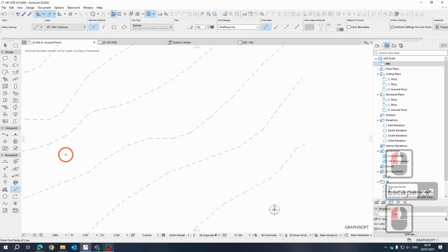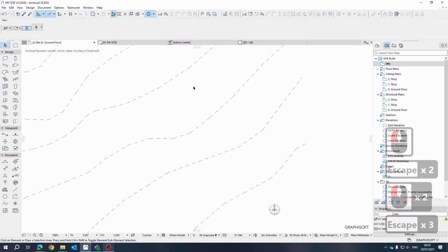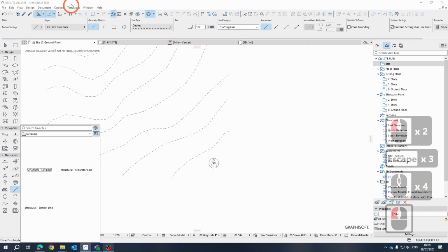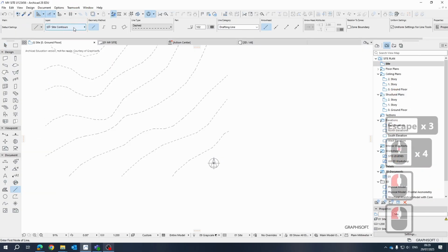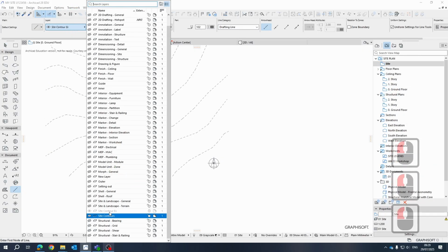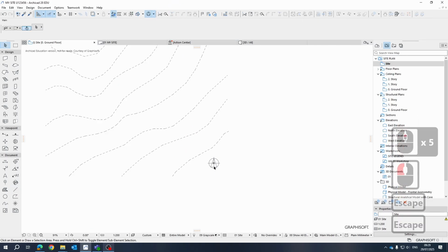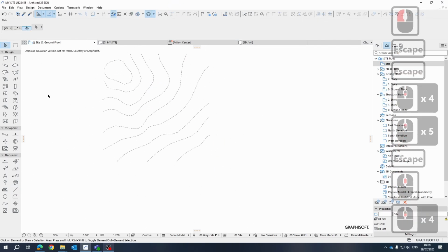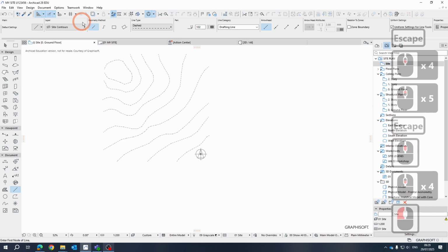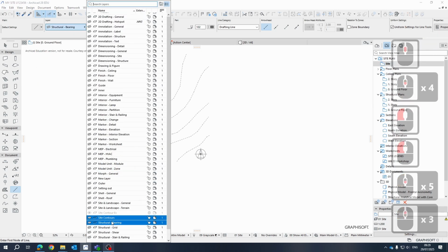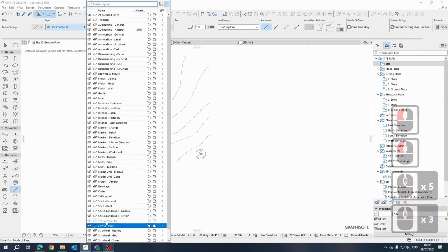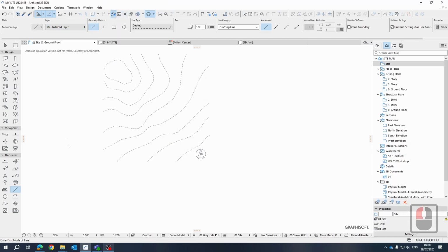So if you've used a series of line work, it's on a locked layer, so line work. Just make sure that you're using the correct layer, because all the layers are off, and you can see site X. So maybe we'll get to that in a minute, because for this line tool, you must just find the right layer to use. Okay, so this is the layer that I want to use, but it's currently locked, so I can't use it either. So I'm just going to use this Archicad layer for now.